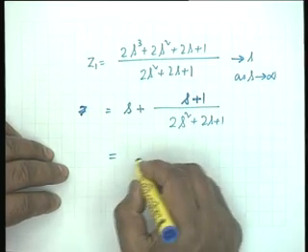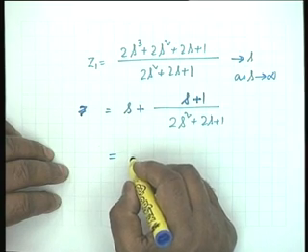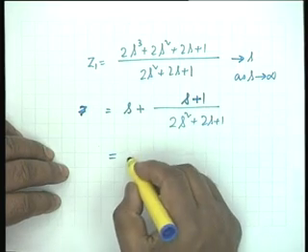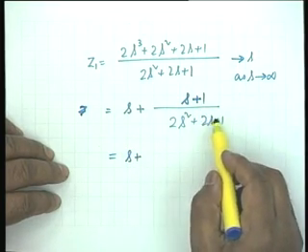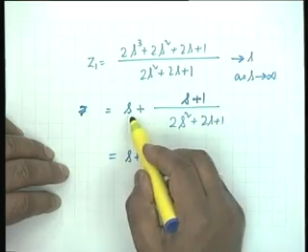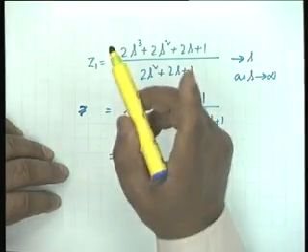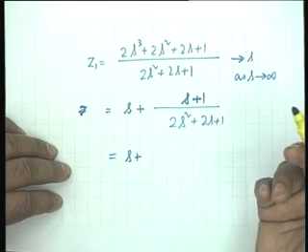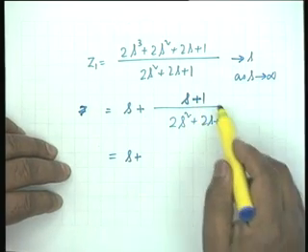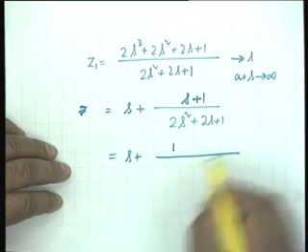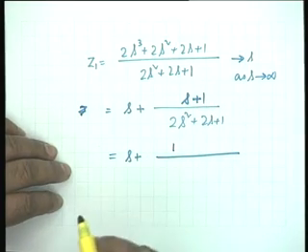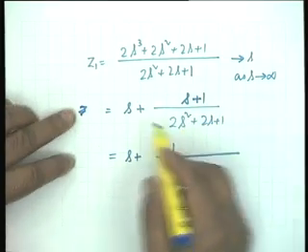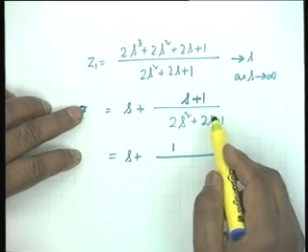So the next thing that we do is, please follow this carefully, because this is going to be a very important tool in your hand as far as synthesis is concerned. Now you see that the remainder function, after you remove s, the pole at infinity, cannot have a pole at infinity. It has a 0 at infinity, isn't that right? As s tends to infinity, it is a 0, which means that the admittance shall have a pole at infinity. Is that clear? If the impedance, this is an impedance equal to impedance plus impedance.